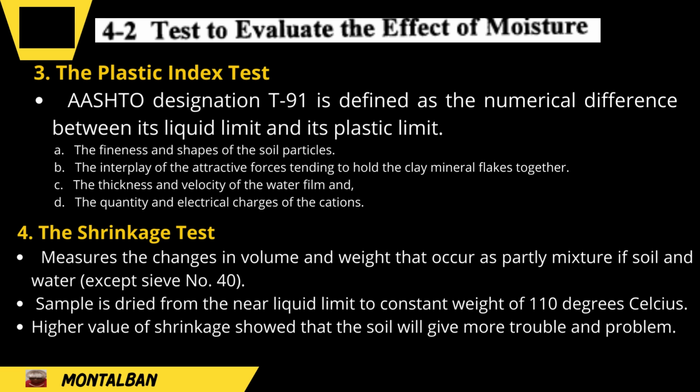On the contrary, for a soil that is high in clay or colloids, more water will be required before the attractive forces are overcome and the strength of the mass is destroyed. In this case, the plasticity index is numerically high.